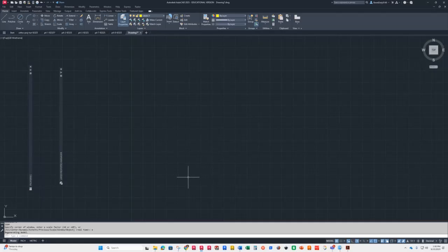And for this one, I'm not going to worry about line type scale yet, but I am going to go ahead and draw our L. Why not? That's the easiest thing to do for the front view. And since I said I'm going to do a right view, then I can just start somewhere here on the screen. The bottom of it is a 20. You got 50, and then you got 15, and probably should have gone the other direction.